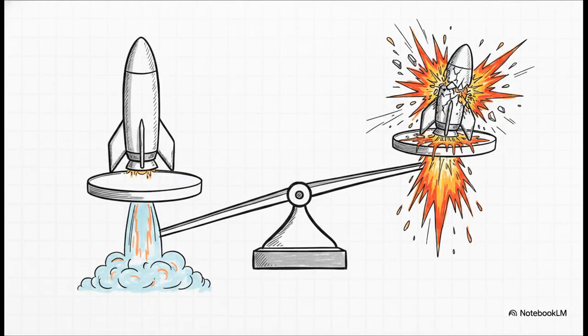So the crucial point is this. You can't just maximize performance blindly. Pushing chamber pressures and exhaust velocities to their absolute limits creates astronomical thermal and mechanical stress on the vehicle. Engine design must ensure high combustion efficiency without the flame becoming unstable. They have to minimize pressure losses, all while guaranteeing the structural integrity of the vehicle under extreme loads.